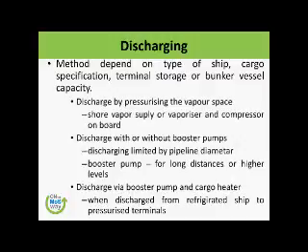So, discharge without booster pumps. Of course, we normally do not use booster pumps on the vessel, but if you want to give pressure to the liquid, we may use them. Normally on LNG carriers we do not have booster pumps, but it is one of the possibilities. And of course, on LPG carriers we do use booster pumps.